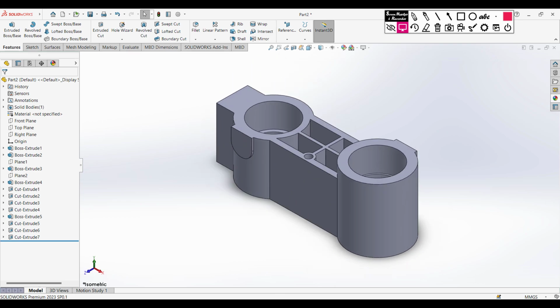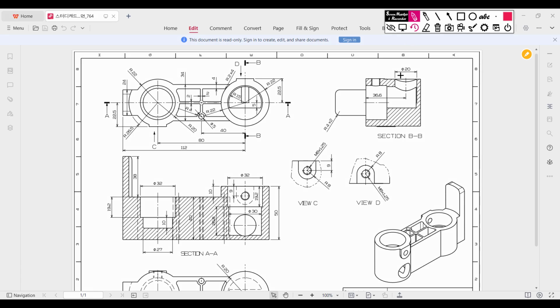Let's go back to our sketch again. So this time in our sketch, we'll do this portion, extrude boss. For drawing this portion, from this center point I'll draw a circle, and this circular profile has a dimension of 26.5 unit. Then I will use the convert entities tool to convert this line, and convert this line. Then I will trim away all the extra portion. Then I will extrude boss it to 38 unit.